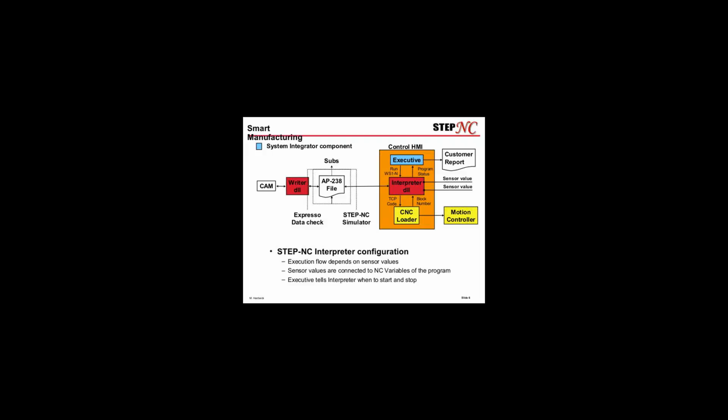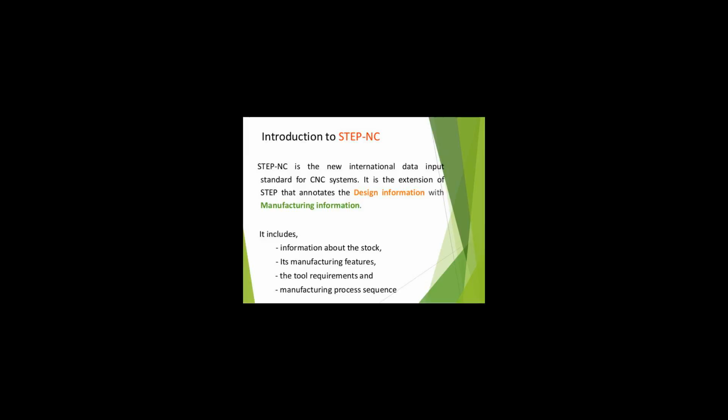A series of traceability extensions have been proposed for linking STEP NC machining programs with sensor feedback and machine state information during execution. The National Shipbuilding Research Program, NSRP, has also hosted work to implement a prototype that connects a shipyard design system to plate cutting using STEP NC. This work involved extending STEP NC to steel plate cutting and marking using lasers and plasma torches.